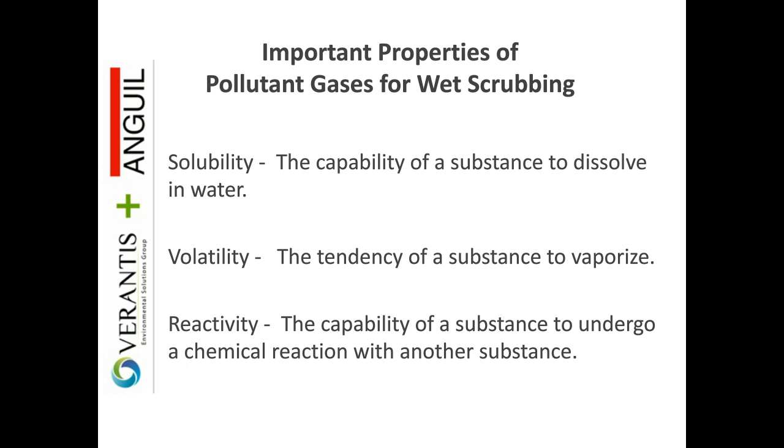If you can get the material into aqueous solution and it can be rapidly reacted with a reagent like sodium hydroxide, for instance, then it's likely also a good candidate for wet scrubbing. If the gas is fairly non-reactive with typical chemicals available for neutralization, or it's not reactive at a rapid enough rate, then you probably are looking at a different technology like a thermal oxidizer to control that compound.